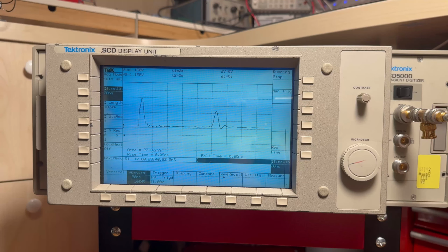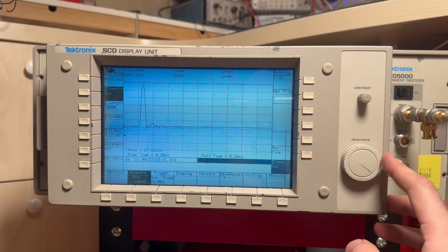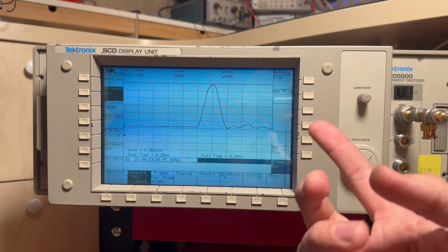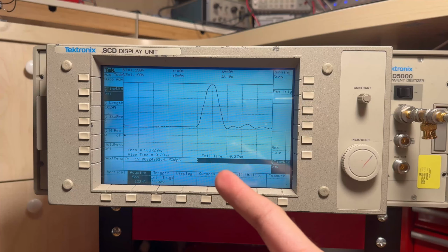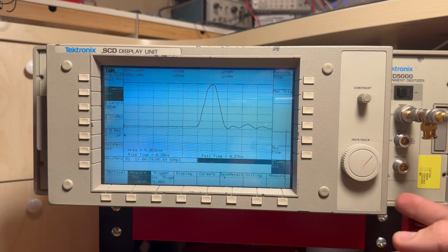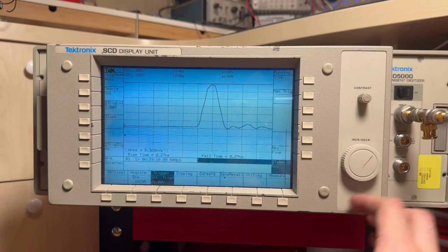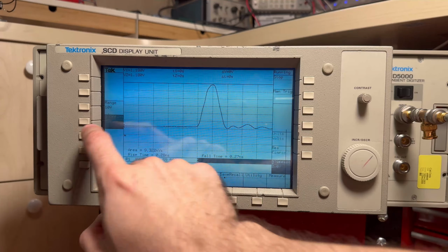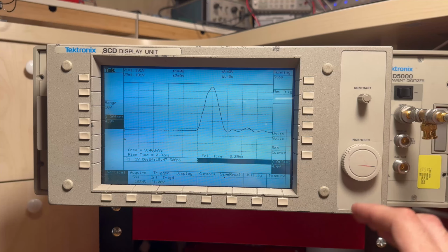Again, as I said, this thing was meant for lasers and stuff like that. And you can see now that I removed that troublesome adapter, the pulse looks a bit better, and actually the rise time is a bit better, so probably some extra inductance and stuff like that in the trace evened it out and made it behave a bit better. Let me just move the pulse itself a bit lower, so I think it's this way. Yeah, everything is kind of backwards.